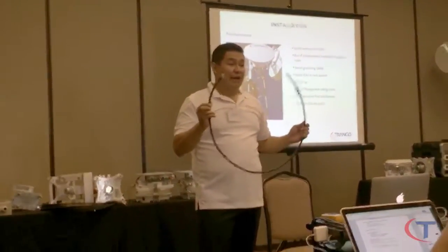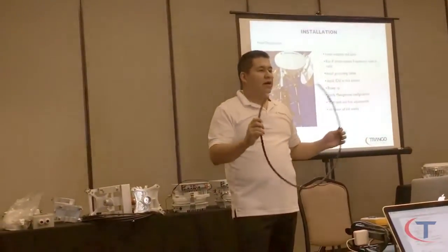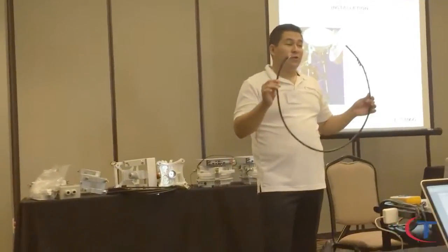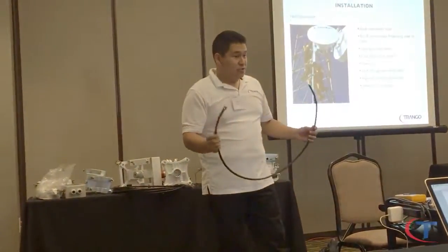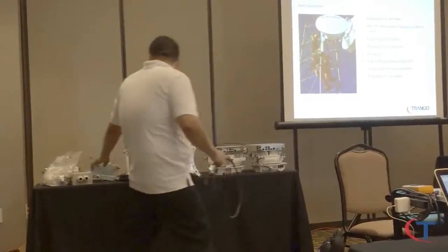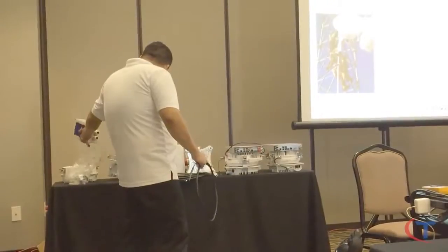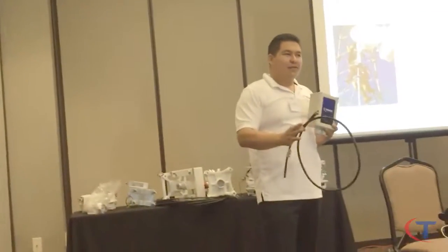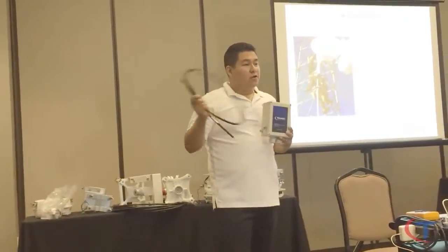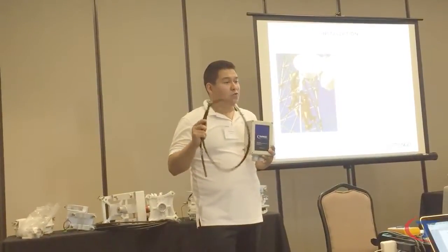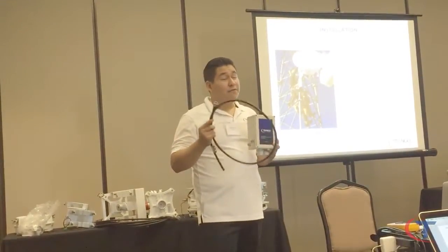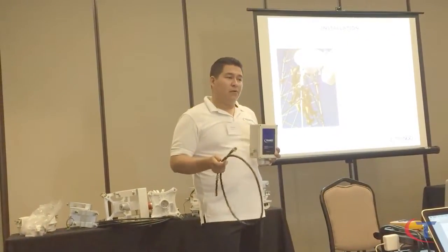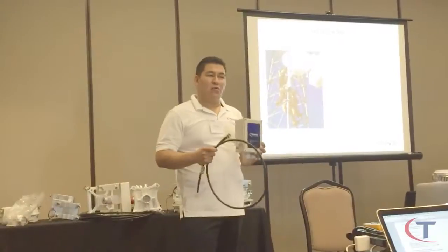Now this is designed to go 1,000 feet, so you can have your IDU well behind the actual tower with no problems for split mount systems. For the all-outdoor systems, from your PoE box, it's recommended 250 feet all the way to the radio. I know standard is 300 feet for Ethernet, but the longer you go, it's a PoE device. You are going to drop a little bit of power, so 200 feet, 250 feet is recommended. You can go further out, but what's going to happen? You're going to drop power, and instead of getting a gig connection, you're going to drop to 100 meg connection. So I wouldn't recommend it.